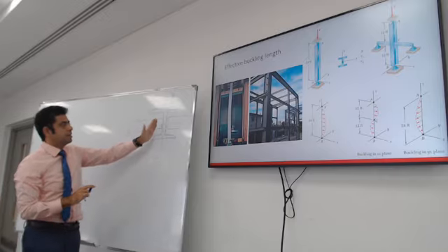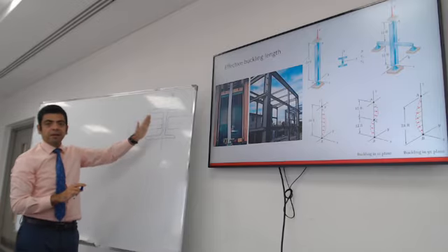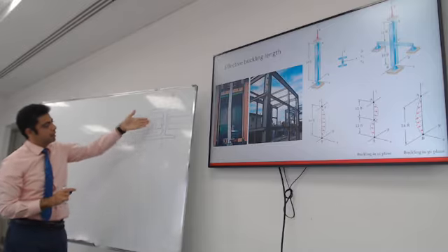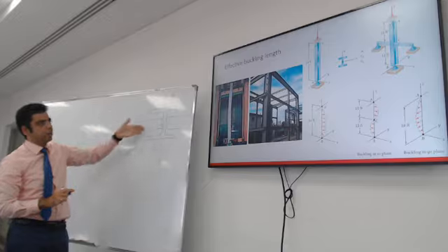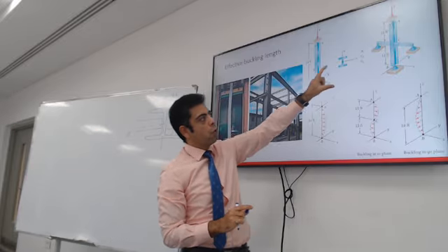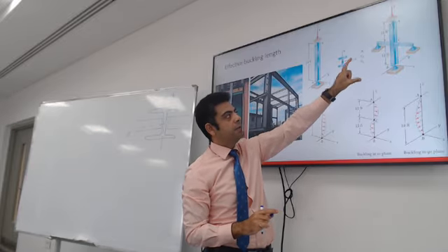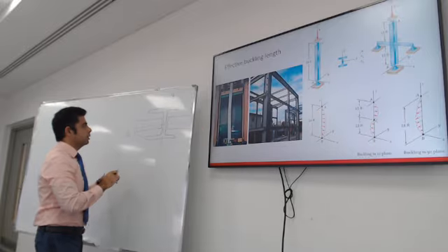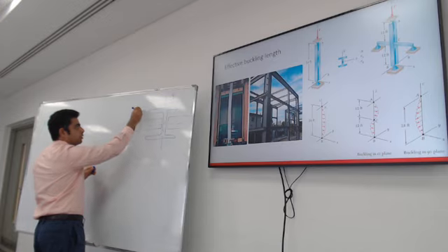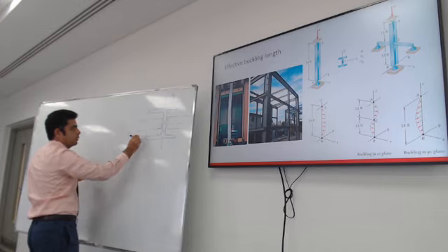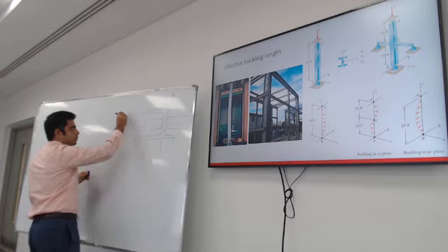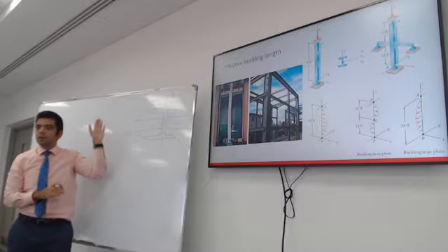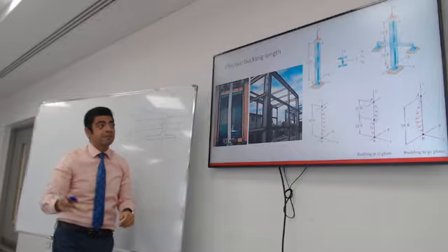So, is the effective length, the effective height of the column, when it's buckling about Y, meaning in the XZ plane, the full length or half of the height between the beam and the supports? When it wants to buckle in this direction, the dotted line. Do you see how at mid-height the buckling of the column wants to shift? Half. Yes, that is the correct answer.